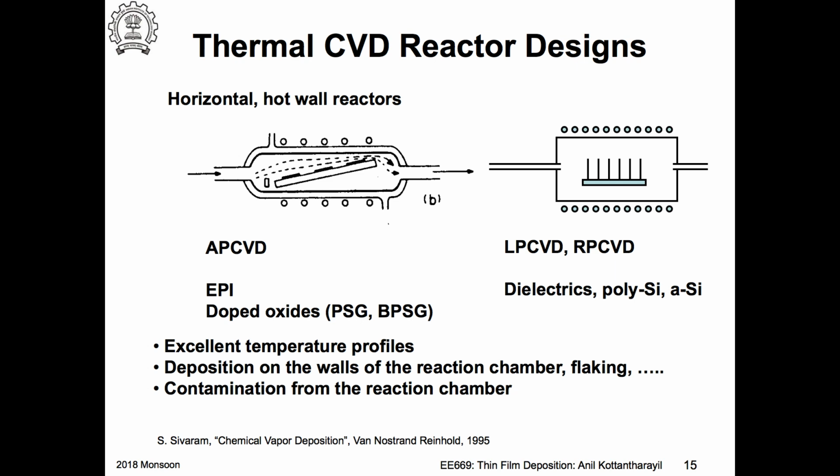If you take a furnace tube, it may be this long. The typical process is to take it and put it in an HF solution, hydrofluoric acid solution. HF will of course etch the quartz also, but the quartz wall of the furnace is fairly thick, and what you have deposited inside will not be so thick, so I can etch it. I'll keep it for a couple of days and then take it out. But hydrofluoric acid is fairly dangerous, so we have to be very careful.